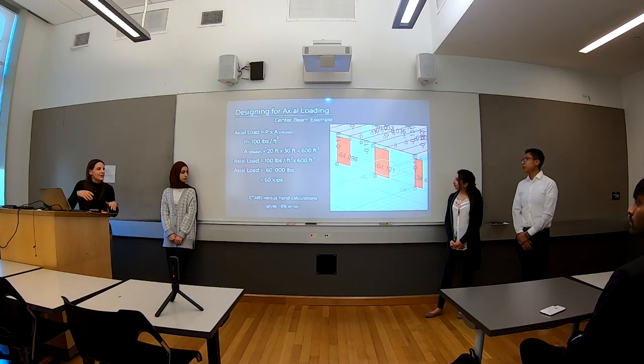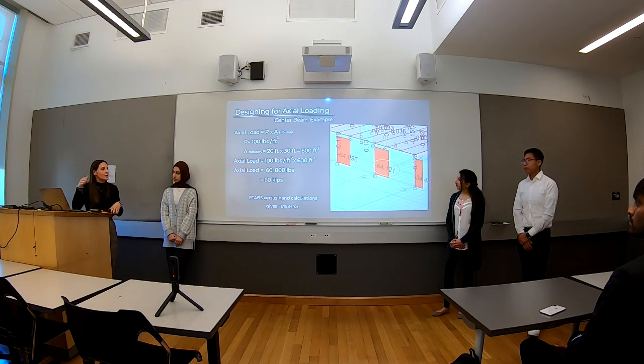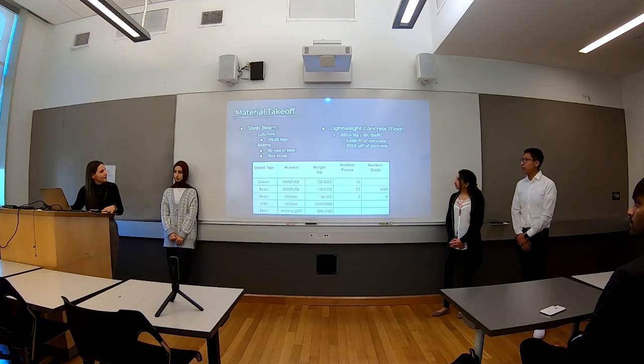So we looked into why this may have happened, and in our actual ETABS model, you can see that the floor framing overhangs past the columns slightly. So this is automatically included in the ETABS calculations, but it's not given a definite length of overhang, so we didn't consider that in ours. But since it is just off by a little bit, it still passes the check.